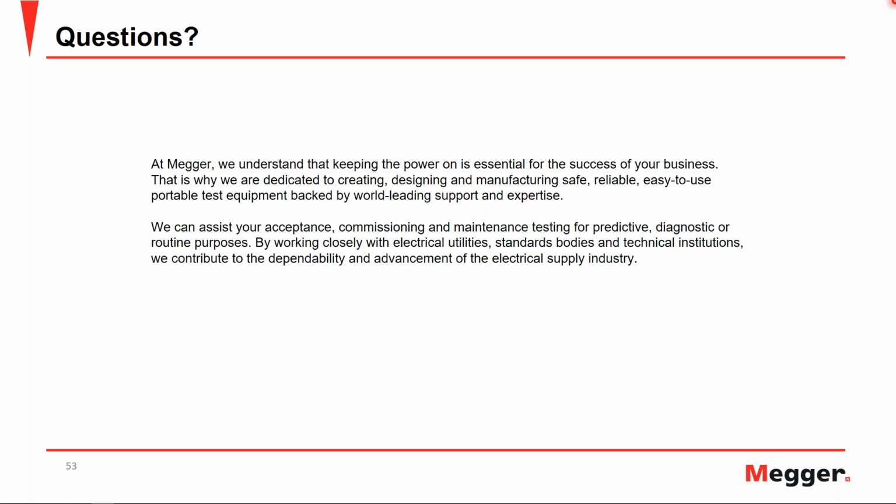To answer that question, I would go back one step: the purpose of power factor testing is to identify the condition of the insulation, and you can check the condition of insulation with different test methods. There are DC insulation tests available.